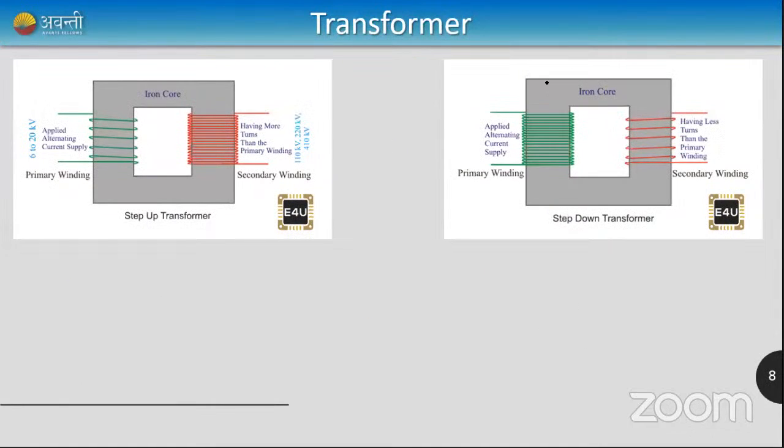Okay. So now I can tell you about the step-up transformer and step-down transformer. How can I increase the voltage and how can I decrease the voltage very easily? For example, take E2 by E1 is equal to N2 by N1. You can use P or S or 1 or 2 or anything, whichever is comfortable to you. Or very simply, I can write E is directly proportional to N. EMF is proportional to the number of turns.